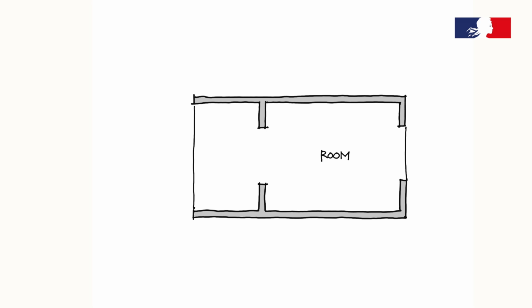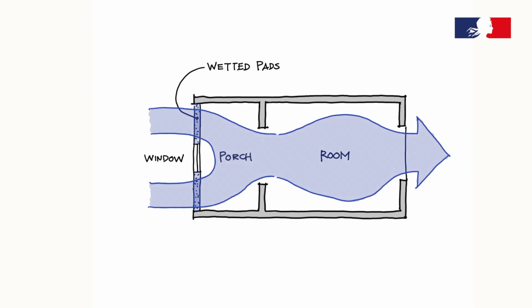Wetted pads made of fibers can be incorporated into building facades. We can design our buildings with an attached porch that forces the air to pass through these wetted pads into the spaces. The occupants need to know how to operate the systems, such as supplying water to the wetted pads during the operating hours, especially during the day.